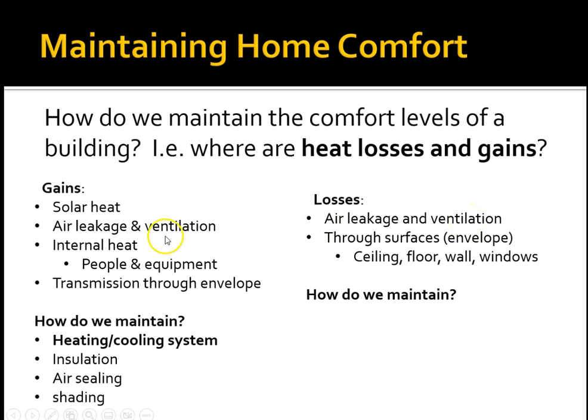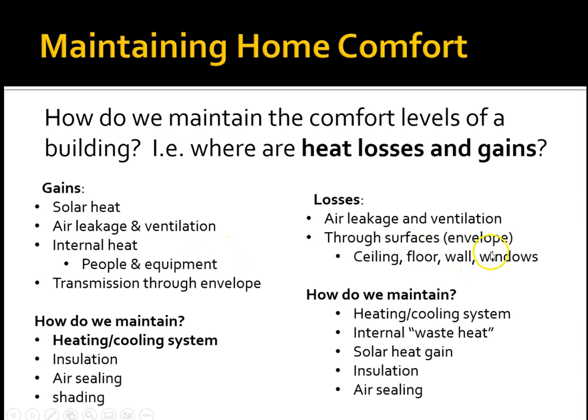But also through the surfaces, just like here, through the envelope, same thing. If it's warmer inside than it is outside, that heat's going to move through the walls and the ceiling and so forth. Okay, so it's sort of the flip side of the gains coin. And how do we maintain? Basically the same thing. Heating and cooling system. We can utilize internal loads. We can utilize solar heat gain to warm up a building passively, which we'll talk about. Insulation, air sealing, all these things